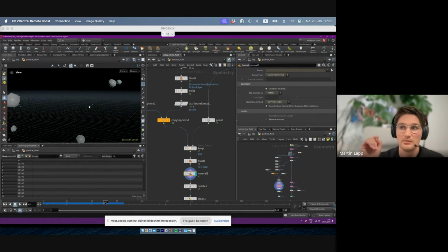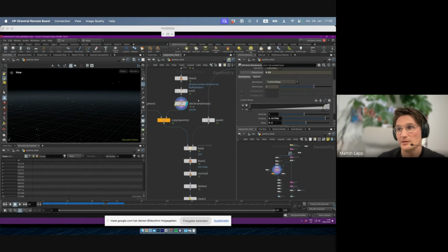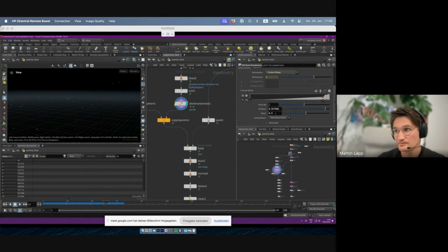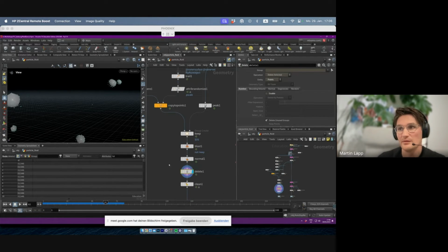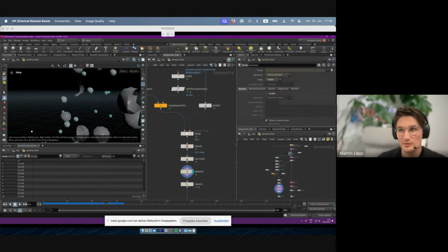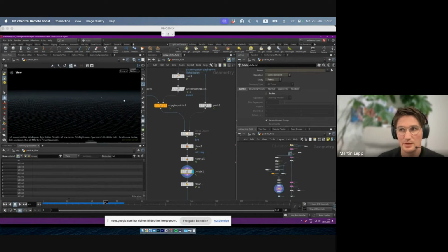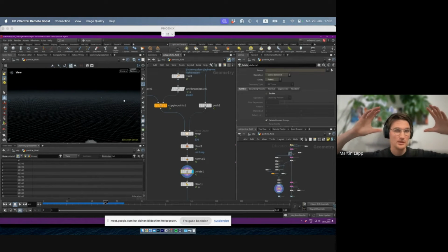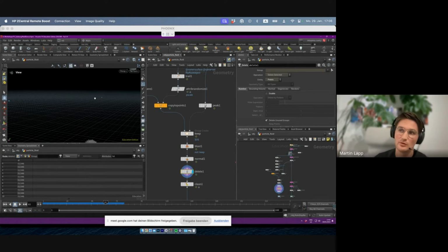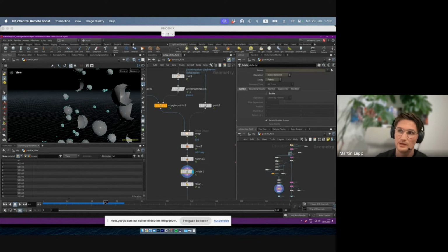And because I gave my particles here a p-scale attribute, which is actually not that small, 0.5, it happens sometimes that you think you just render these spheres, but there is a point. If the point has a big p-scale attribute, if this is set to 1 meter, you get a 1 meter ball in the midst of your render, because this little point that you barely can see is interpreted by the p-scale it has.